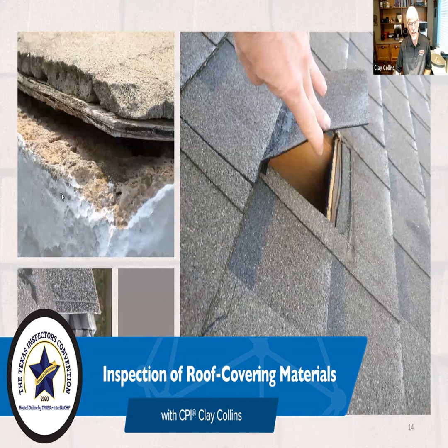Workmanship. Here you have where they sliced through the shingles at the hip, and they sliced through the underlayment as well. Many times when you see this condition, the installer's solution is to take that same utility knife and slice it. And then that's their way of getting rid of the high spot, but it is not an effective way of installing the roof cover.